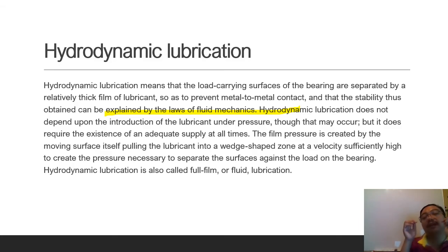You should have some basic knowledge of fluid mechanics. Then you can understand this subject better. Hydrodynamic lubrication does not depend on the introduction of lubricant under pressure, though that may occur, but it does require the existence of an adequate supply of lubricant at all times. The pressure is created by the moving surface itself pulling the lubricant into a wedge shape.